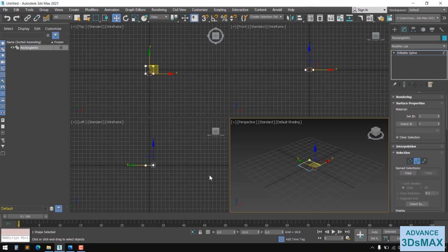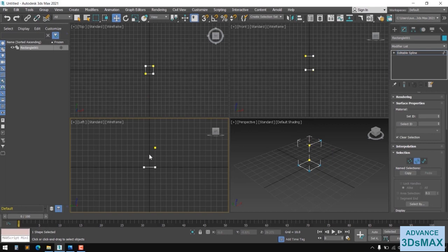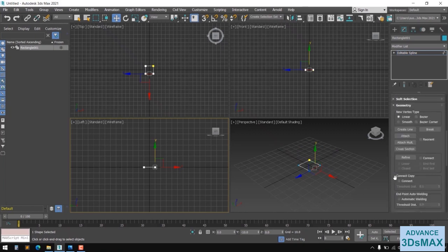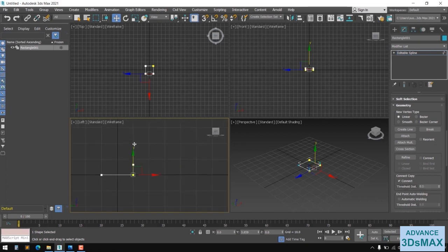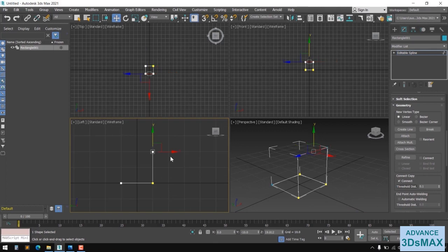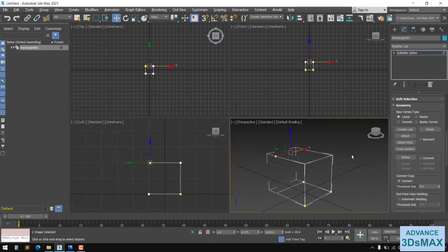If I press the shift key and click and drag in the Y direction, it creates a copy, but the connection is not available here. So we choose the copy connection tool from the command panel. It's a copy command tool, enable this. Then click and drag in the Y direction like this, so it creates segments. Then repeat again. We complete the first frame.